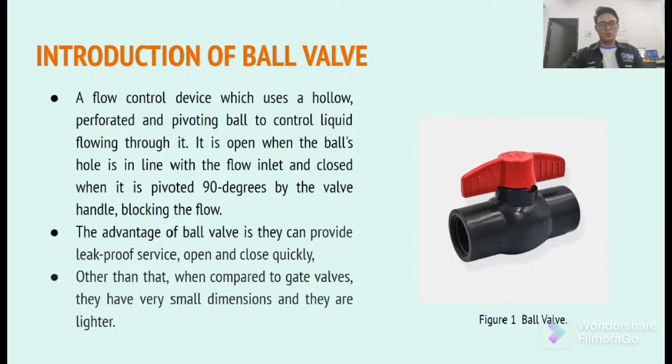And what I want to introduce about our product is a ball valve, which is a flow control device which uses a hollow perforated and pivoting ball to control liquid flowing through it. It's open when the ball's hole is in line with the flow inlet and closed when pivoted 90 degrees by the valve handle, blocking the flow. The advantage of the ball valve is they can provide leak-proof service and open and close quickly. Other than that, when compared to the gate valve, the ball valve has a very small dimension and is lighter than